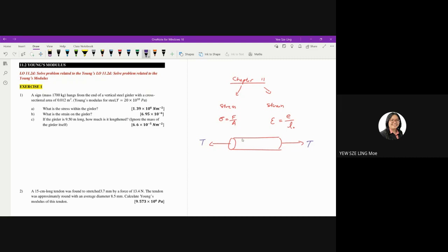And remember, if you want to calculate the stress, the area is not the surface area of the whole object, the whole string. So you don't calculate the surface area of a cylinder. What you have to do is look at the diagram, look at your object, and identify the area that is perpendicular to the force, which in this case is just a circle right here. This is the area that we're going to use in our calculations.